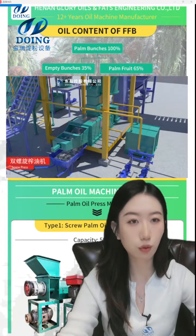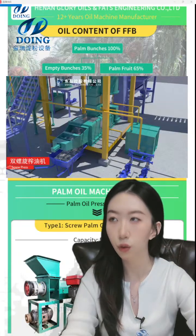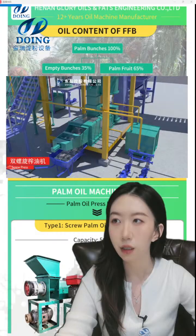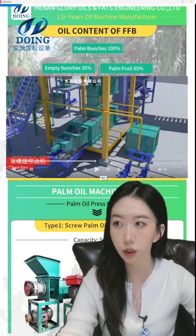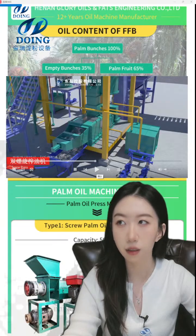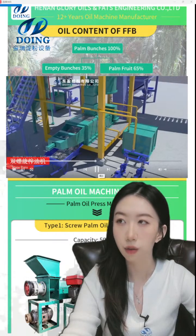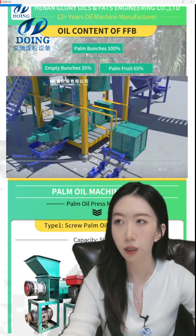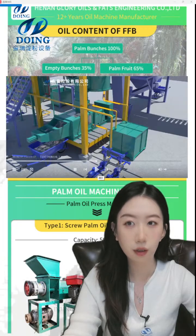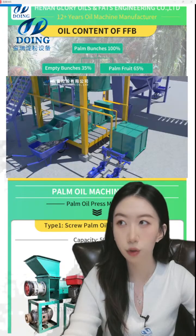This is a double screw palm oil presser. In production line, you always use the double screw palm oil presser because you can see there are two screws. They can move relative to each other, and the oil will be discharged. Oil yield is higher, and it doesn't need a worker to control internal pressure.